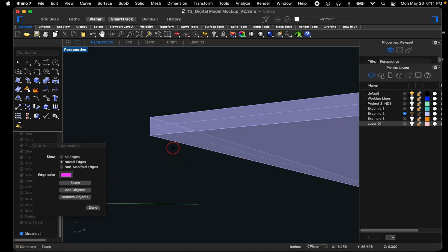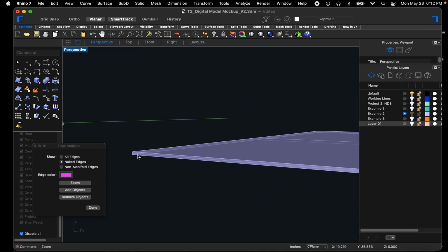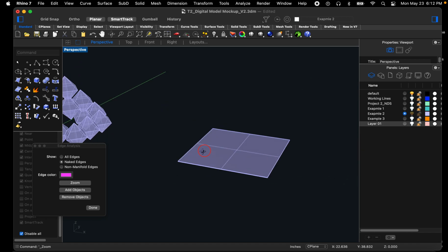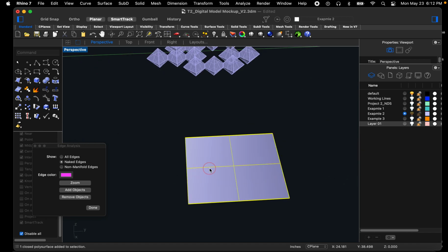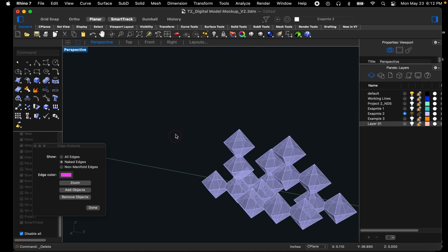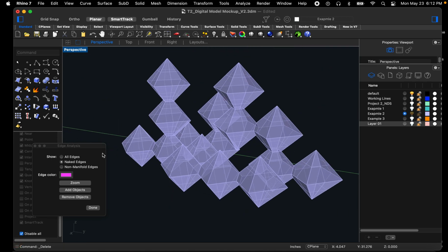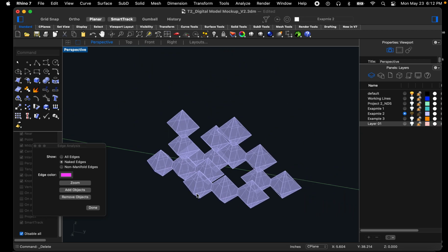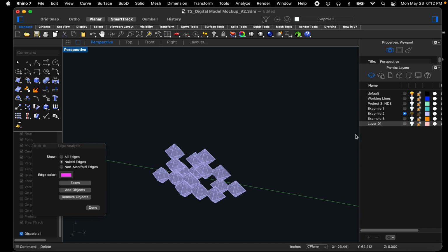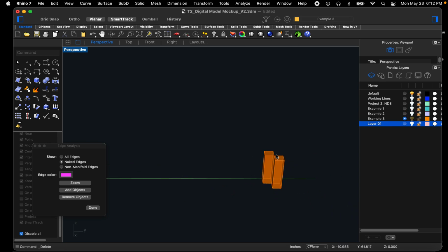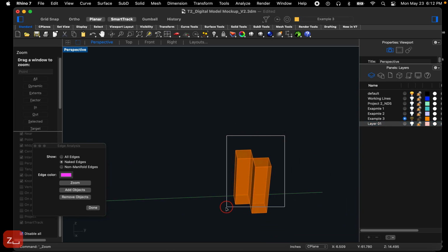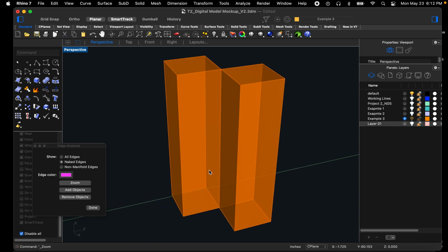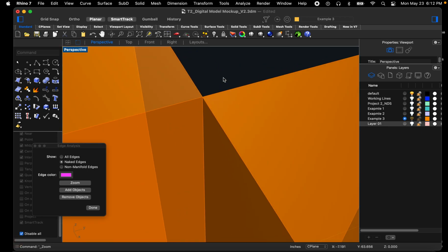Now we've got 5 more surfaces to describe an enclosed space. Okay. So, naked edges. They're a problem. And the edge analyze tool is what we would use to find the areas that would be problematic. Now, a naked edge, turn on example 3. Let's say we've got, these are 2 extrusions, and they are sharing this edge.